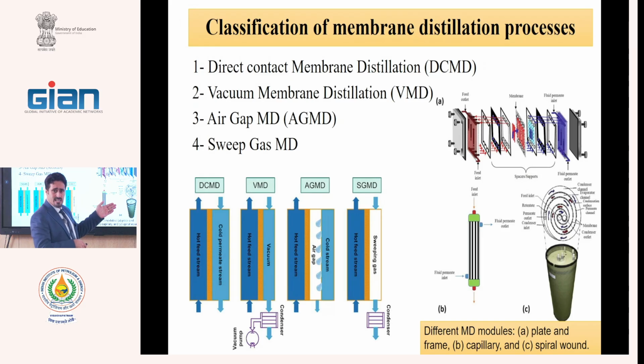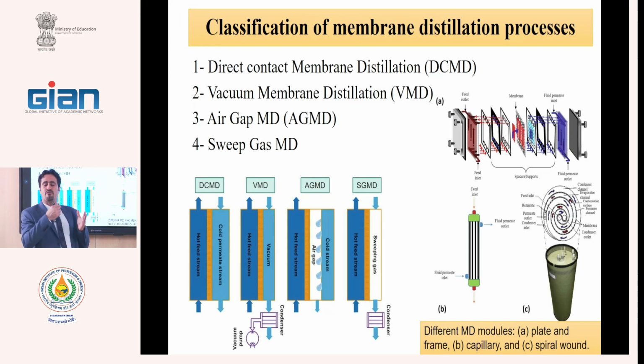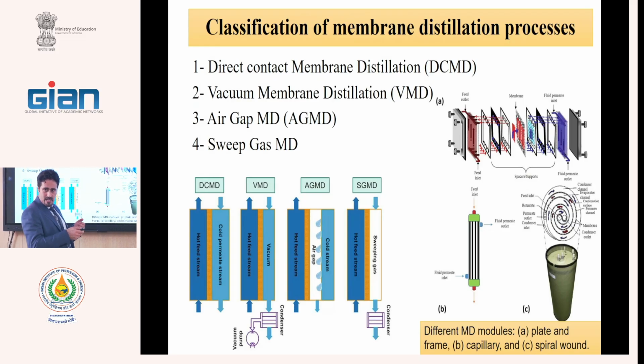This method is not good because the permeate solution can wet the membrane and fill the pores. We do not like the pores filled with water. In direct contact, we have a second stream, and the possibility of liquid going into the membrane pores is increased.